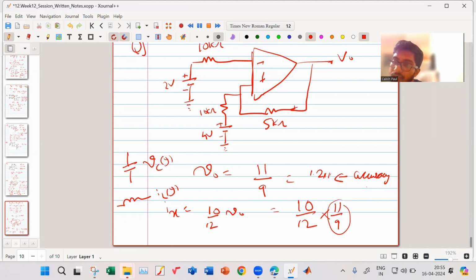Those are the variables you must solve with. These are the kind of inputs that I require. For example, if there is an LC network, then V across L is equal to L into di/dt, so that is coming in terms of I, right? Yes. And VC of t is directly taken across the capacitor. Okay. So in this case, again I need to convert this I of t into V of t, right? Yeah, we have to do.